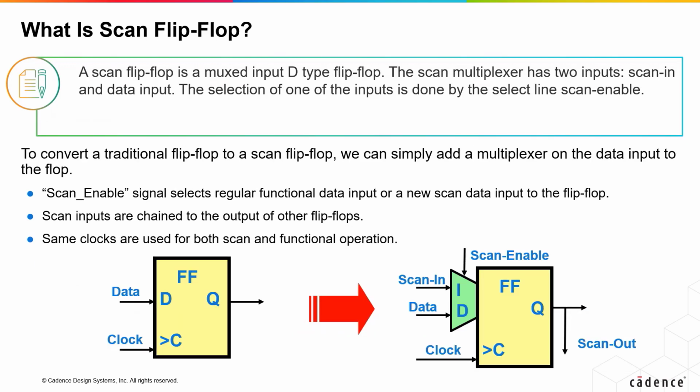How do we create this scan mode? First, all flip-flops in the design must be converted to an equivalent scan flip-flop that has selectable input data ports. A scan flip-flop is a muxed input D-type flip-flop.